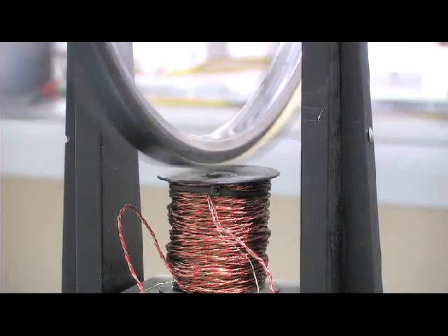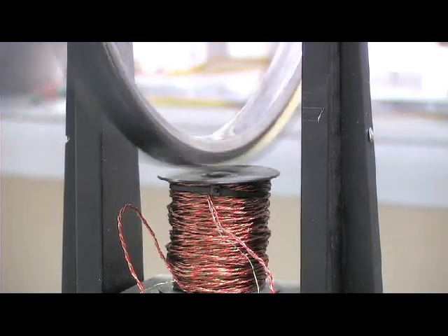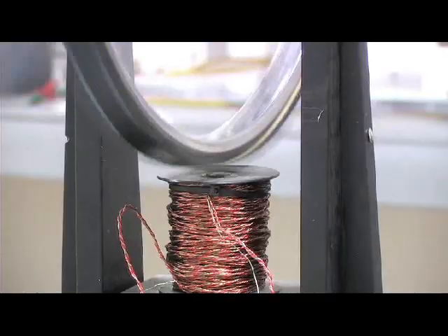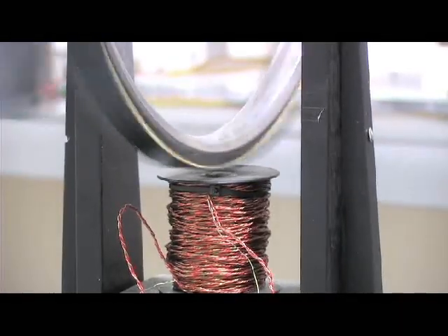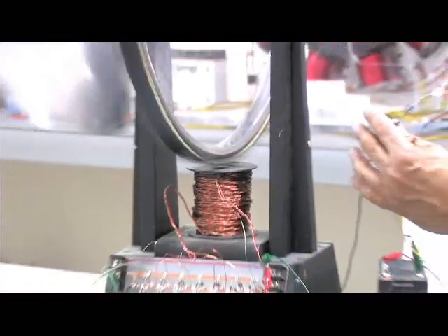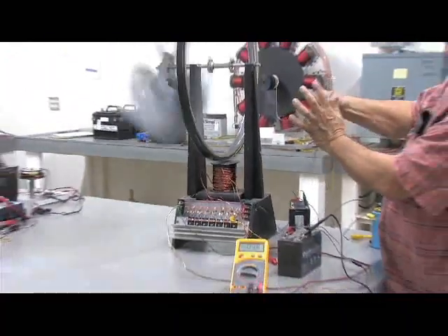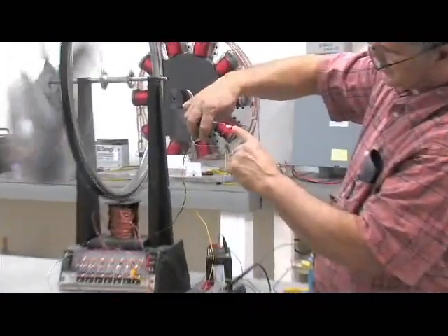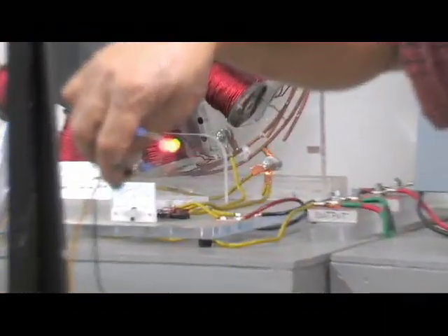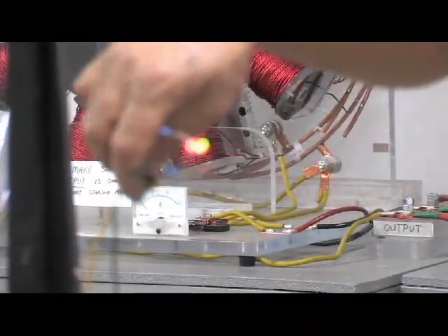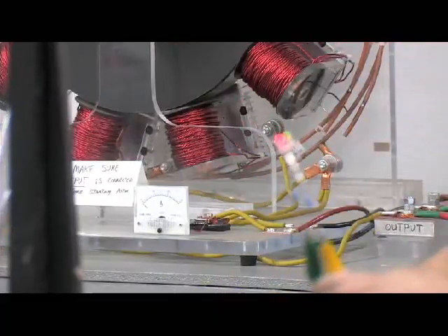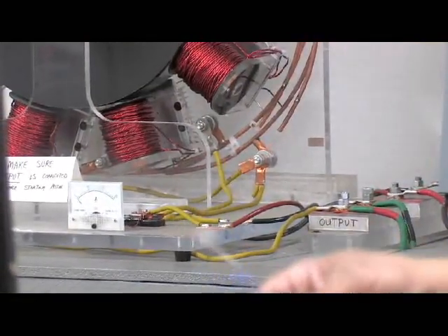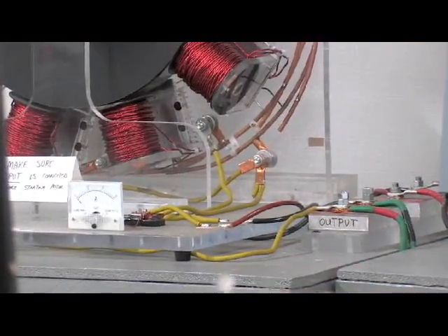See, and so you can make a simple set of timing lights by using two LEDs back to back and a couple of resistors so that you can see the firing across the coil, and you can see it here. You can see one is the charge and one is the discharge. So that's one way you can do it, to find the exact timing.